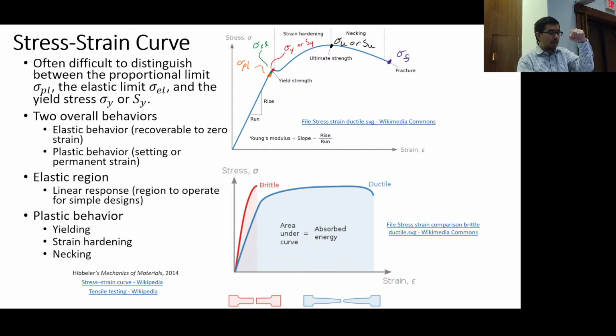And that's kind of the definition of what's happening here, right? Force is not really increasing that much in this region. It's because the slope is kind of flattish, right? And so when that happens, you could get elongation, and if you keep getting elongation, the cross-section keeps going down, right? Eventually you're going to get into fracture. So for many reasons, we design for the elastic regime.